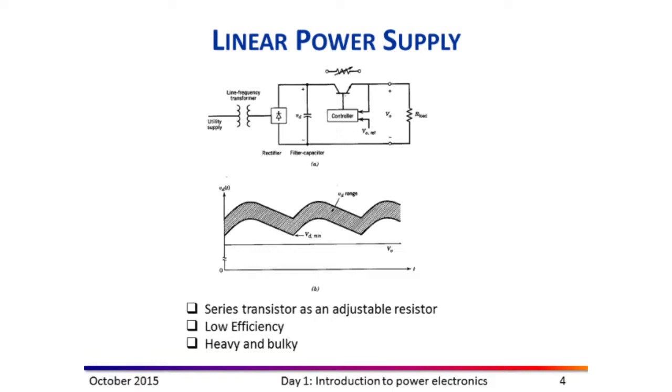So this 5 volt drop also creates losses. Now, what if I do another circuit like this as a switch? I will use the same transistors, but instead of sending the signal like this one, I will operate this one in, you can see, the saturation region. That means I will send enough current to turn it on completely or turn it off completely.